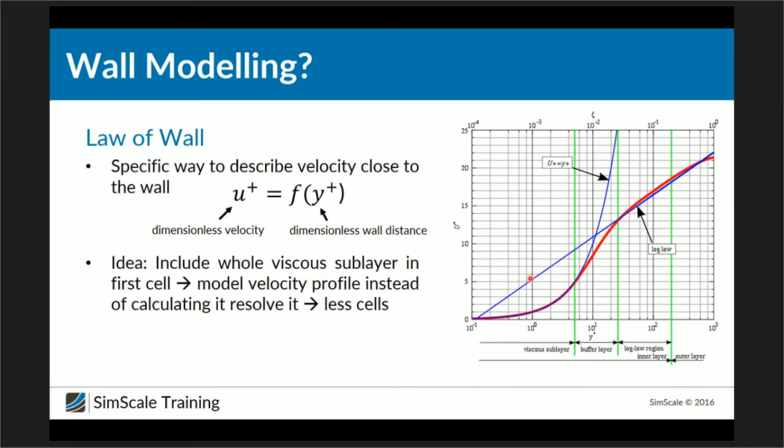To put it in a nutshell, if I want to make sure that I model my boundary layer flow correctly, I need to resolve the high gradients in y direction, and therefore I need a very fine mesh in y direction using the layer elements. There are two options. One option is to directly resolve the full wall velocity profile. Then I need to have a wall distance y plus value of 1, which will lead to very flat cells and a high number of cells in total.